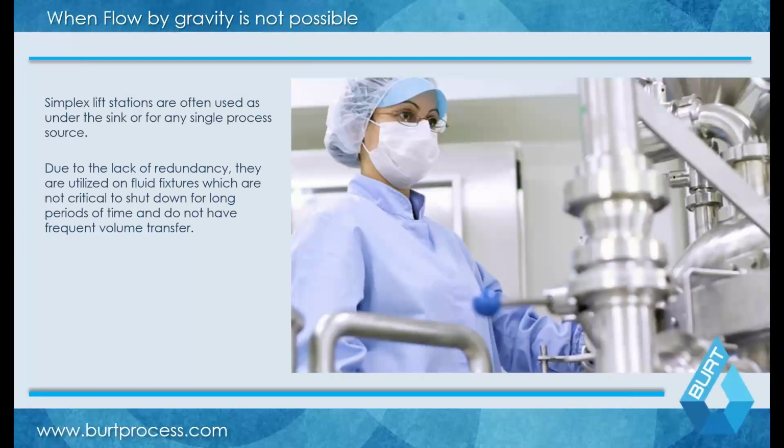Waste lines by gravity, depending on what your processes are, might go underground, for example, or you might have an addition or a laboratory added into your facility, or a new process, where it's just not feasible to have that gravity flow going into your actual pH system. So very often people will utilize a lift-based system in those cases, where you collect it in an acid-resistant or corrosion-resistant lift station and then transfer it into your actual pH neutralization system.